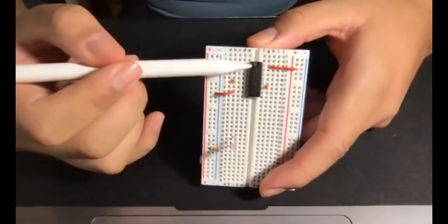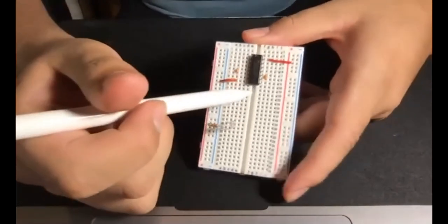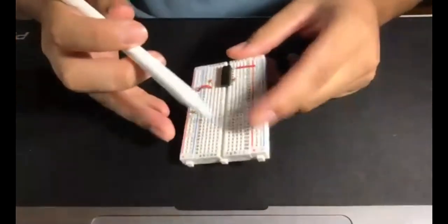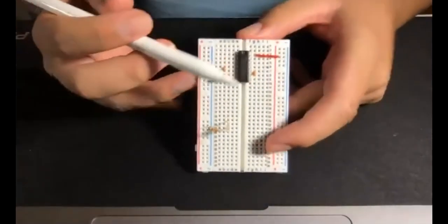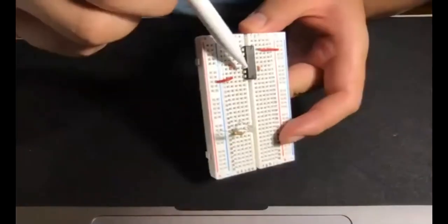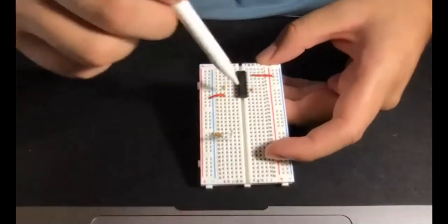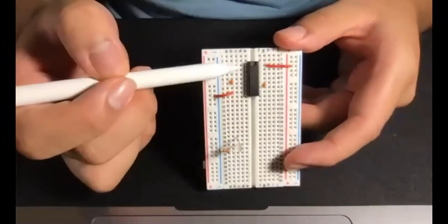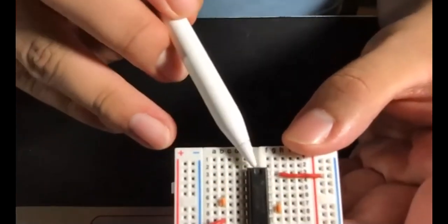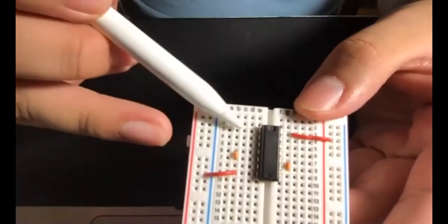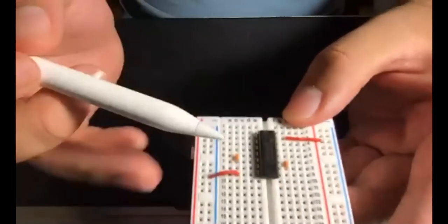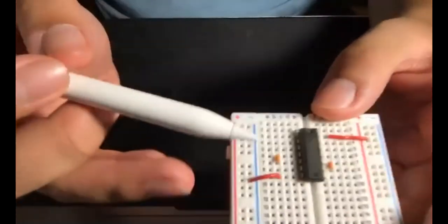So here we have our chip. As we stated before, there's a split down the middle in the breadboard. And this is really made for the integrated circuit chips so that the pins on the sides, the inputs and outputs or whatever they may be, are separated from one another. So starting from the top left, you can see that there's a little notch right here. Like I said, you typically start on the top left and you make your way down here and up here. And I've already made a couple connections here.